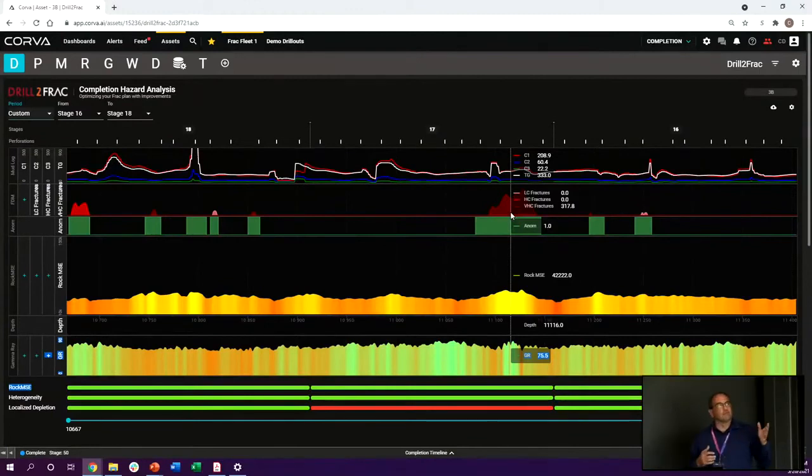In this particular case, when we're seeing very high confidence, usually that's supported by some offset wells. Between high confidence and very high confidence, we would classify those as actionable, meaning we see a strong potential that the extent of that fracture is long enough and the depletion is large enough that it could have a significant impact on the treatment of that well. So that's just a classification of the fractures.